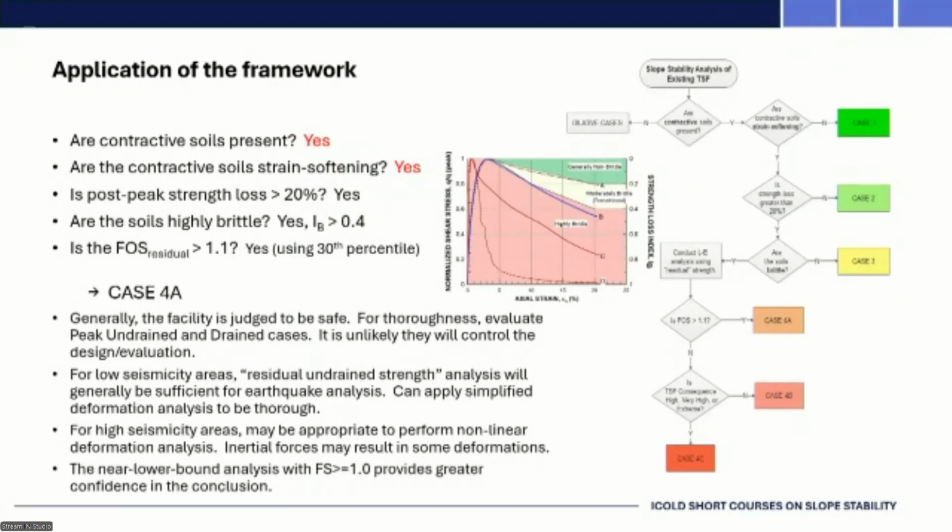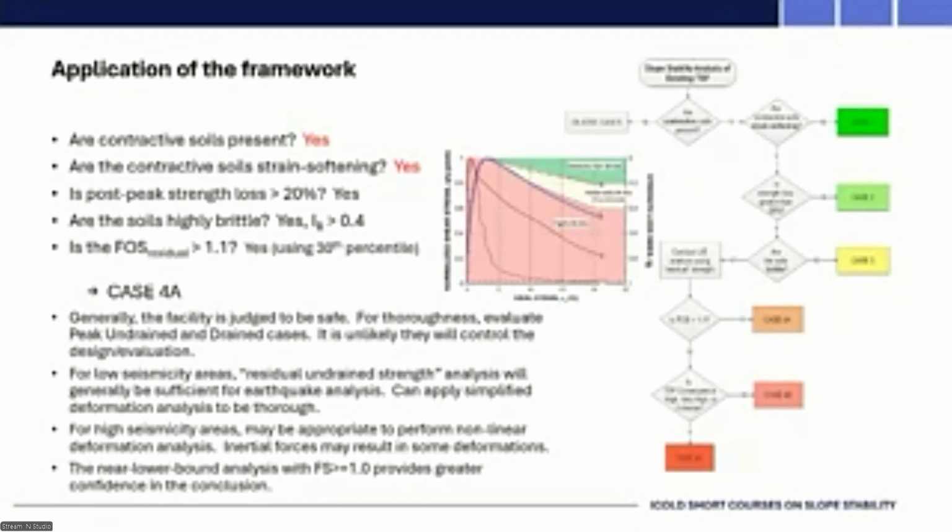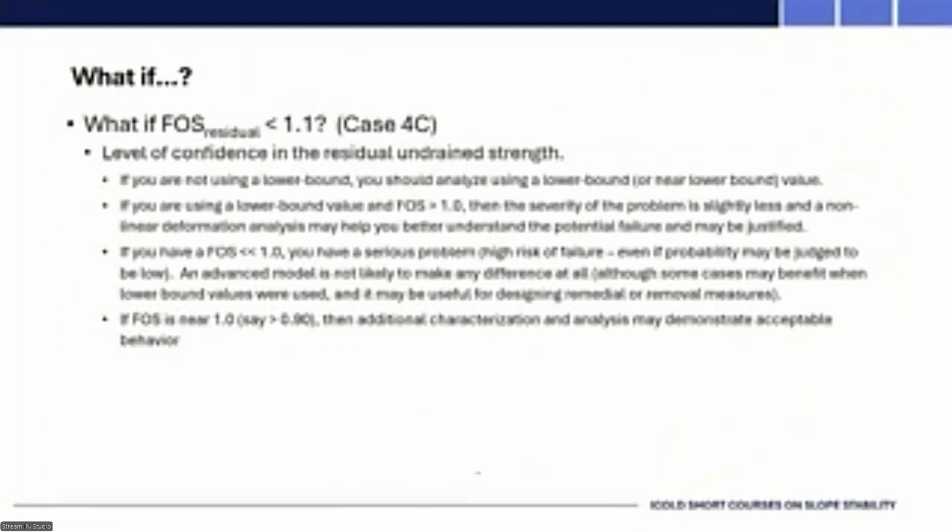So you'd want to, certainly at a minimum, do simplified deformation analysis using Bray-Travasarou and Bray-Macedo, whichever would be applicable to the actual seismic source. Or you may want to do a nonlinear deformation analysis. I would tend to do that myself, and that's actually what we did in the case history.